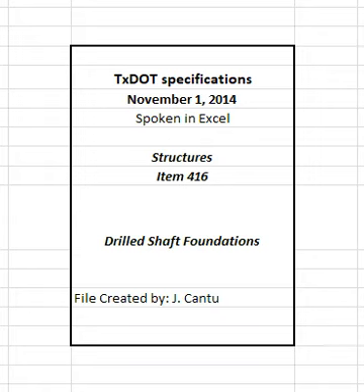3.3 Casing. Use casing when necessary to prevent caving of the material, to exclude groundwater, when slurry is used for hole stabilization, or when required as part of the contractor's safety plan. Provide casing with an outside diameter not less than the specified diameter of the shaft. The portion of shaft below the casing may be as much as 2 inches smaller than the specified shaft diameter. No extra compensation will be made for concrete required to fill an oversized casing or oversized excavation.